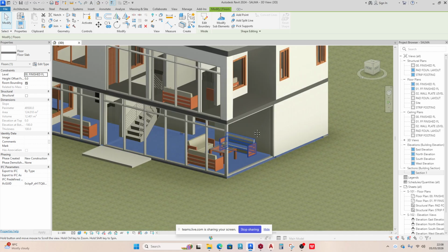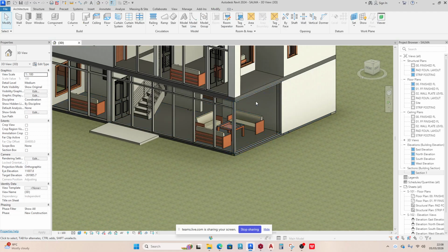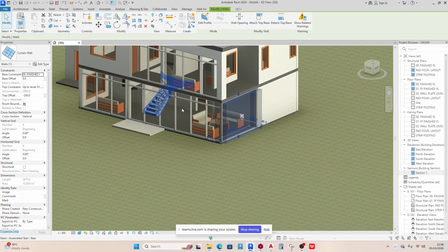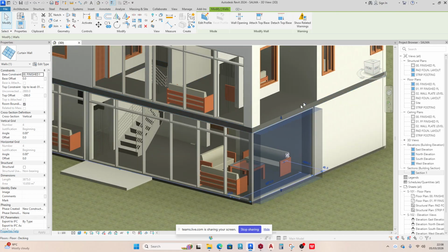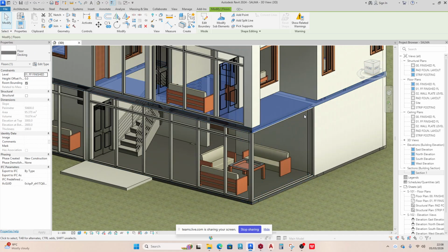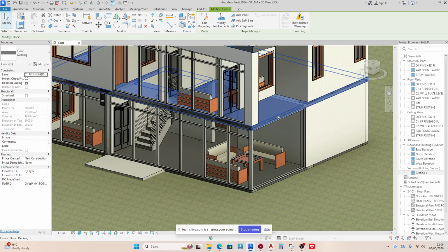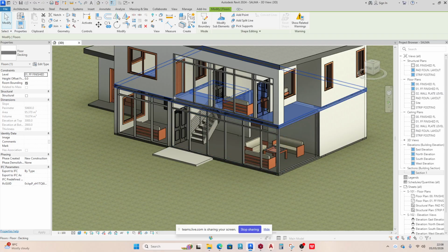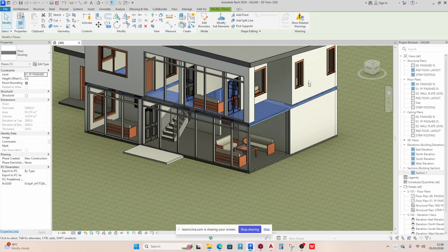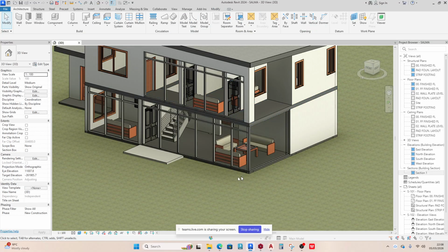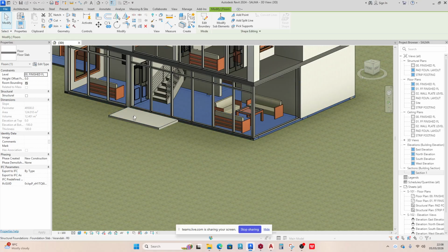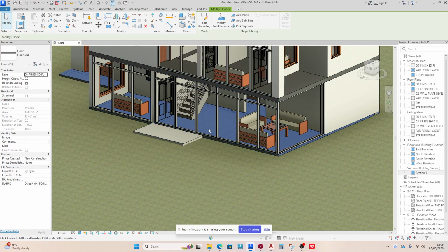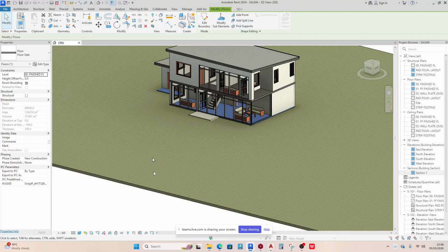These elements that we're seeing over here, it's got the curtain walling, and then of course we've got these masonry walls, and we've got the RC, reinforced concrete slab, and this is a suspended slab. If it's in the air or it's been supported, it's called a suspended slab. However, if it's here, like this ground floor slab, this one is called the foundation slab because it's resting on the earth.